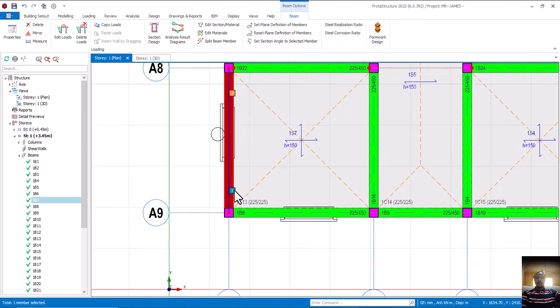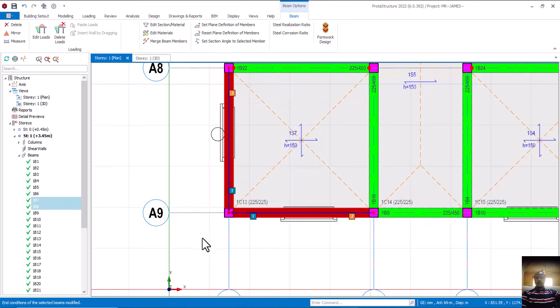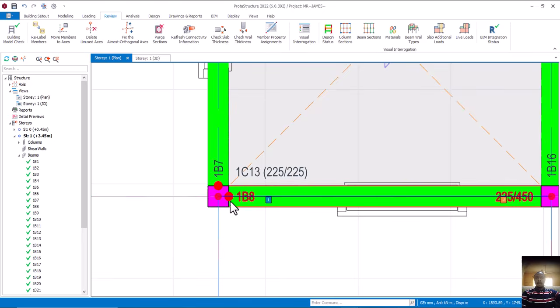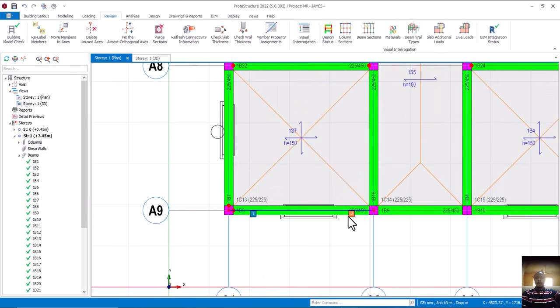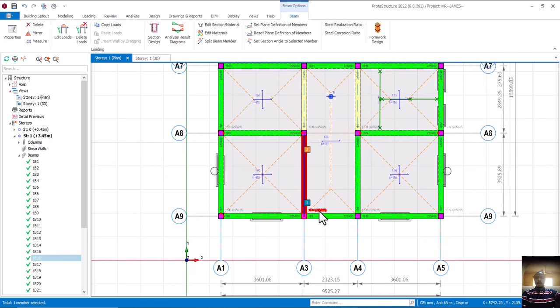Can you see? I can hinge this one, I. Let me click on this. Okay, can you see? I is on this side, and this one is also I. So I can now select these two. Since both of them are I, I'm hinging at I. So I'll click on this one, press my control key, click on this one, then right click and come to this condition and say hinge at left, which is what? Left end. I'll click on it, then click on apply, and then click somewhere else. Can you see now? I've hinged this place. Can you see that this place is not hinged? Is that okay? So that's why it's very important to know what you are doing. So now looking at this one, I can select this one also.